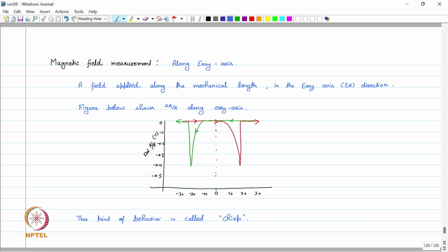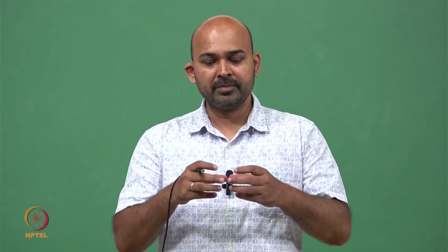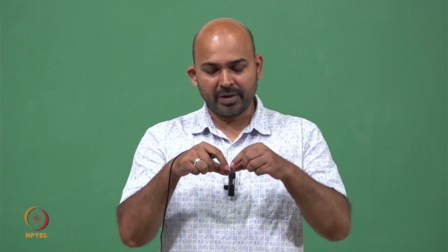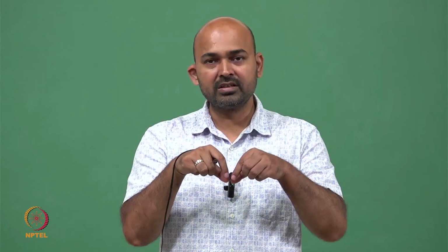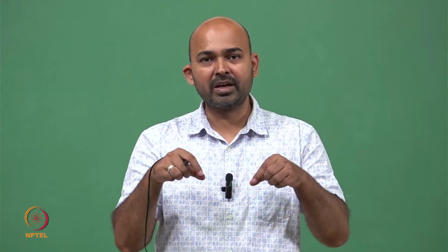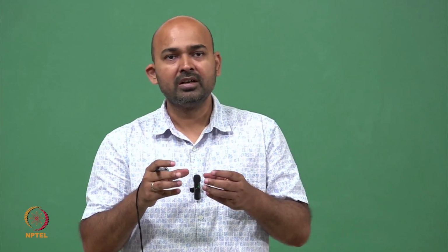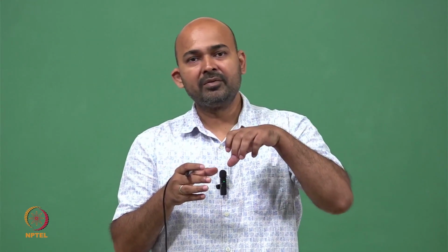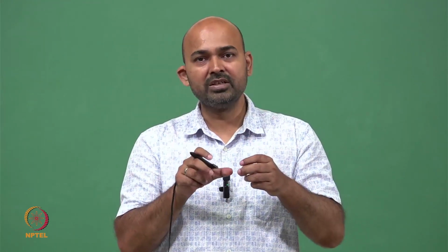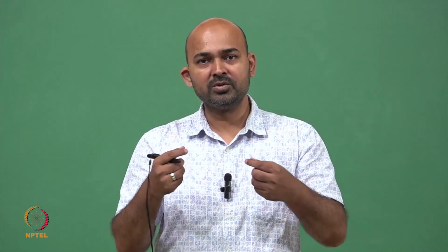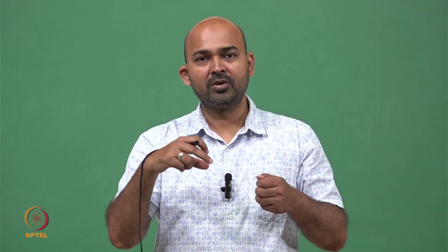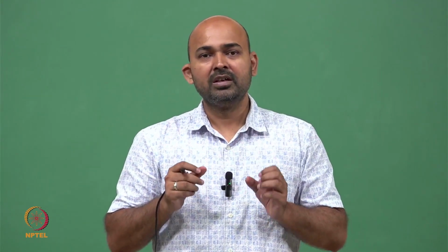So this is how the magnetic field response of these sensors changes. We fabricate the strip, the very thin film of these magnetic material on the substrate, and when we apply a magnetic field, the resistance of these, which we can measure using our biasing circuitry, we apply a constant bias across it and measure the current flowing through this.